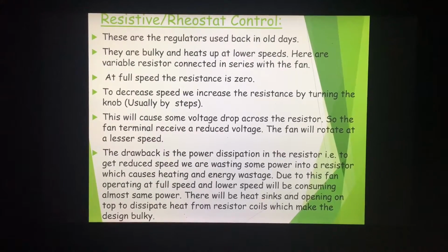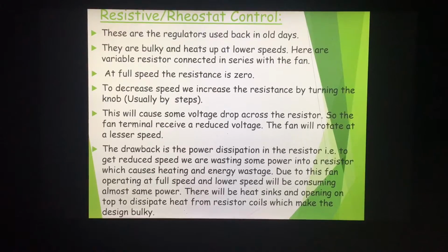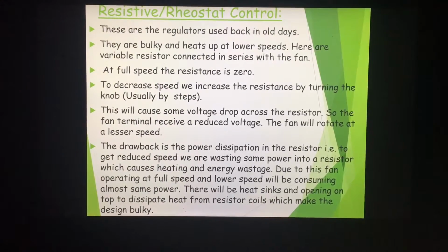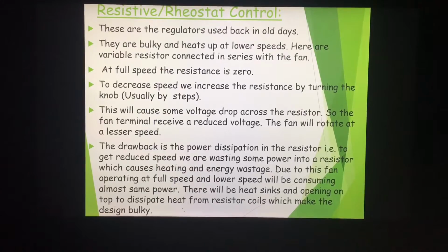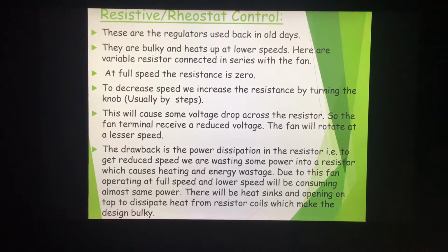The drawback is the power dissipation in the resistor, that is, to get reduced speed we are wasting some power in a resistor, which causes heating and energy wastage. Due to this, a fan operating at full speed and lower speed will be consuming almost the same power. There will be heat sinks and openings on top to dissipate heat from the resistor coils, which make the design bulky.